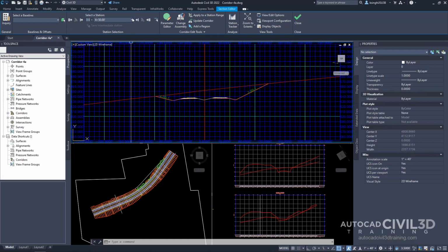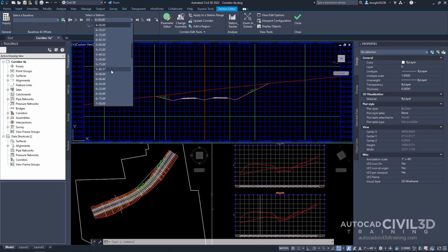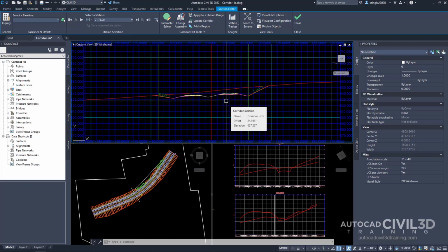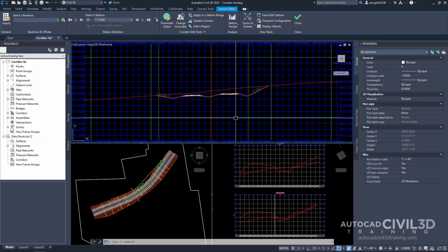Go ahead and go into your station selection and select 775. Notice the super elevation transition. Using the centerline pivot option on a depressed median subassembly causes the lanes and the shoulders to super elevate about a point above the centerline ditch. A straight edge laid against the lane surfaces would pass through the profile grade point.